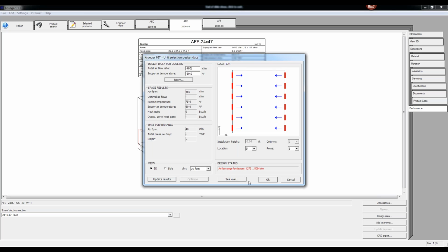And it's telling me, well, you have way too many because you need at least this much air for these numbers. So I'm going to just step these down. Let's go with 1. Let's see. So at 480 CFM, I still have an NC of 25. So that's still a little much. So I'm going to add 1 more. And now we have an NC of 11.